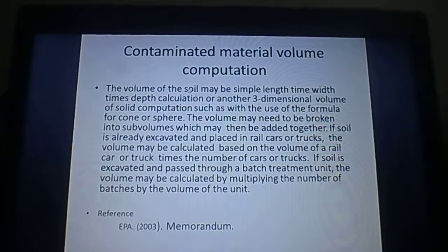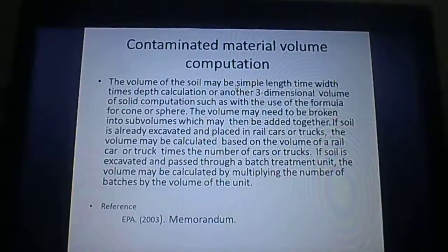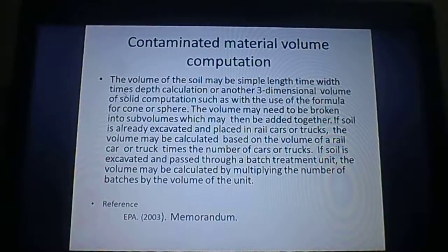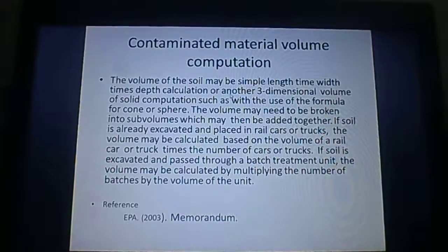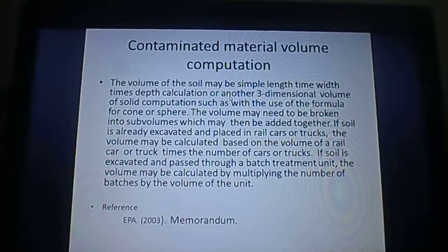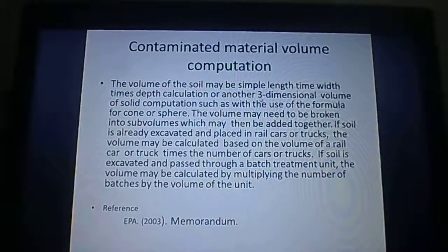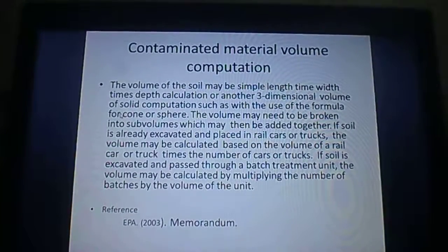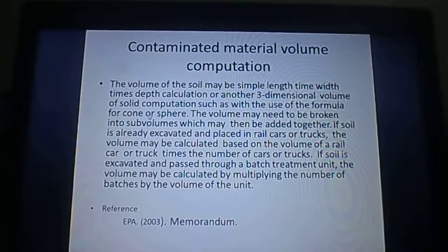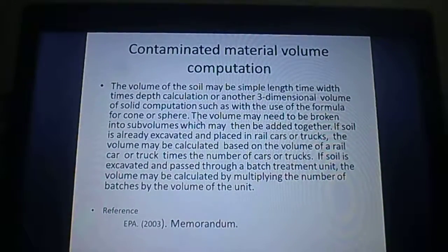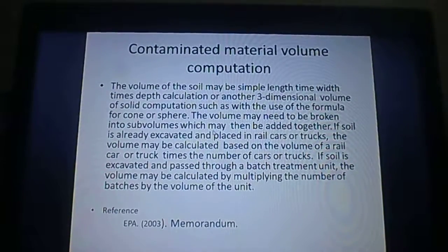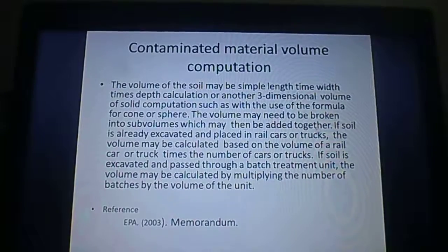The volume of the contaminated soil may be calculated by plainly multiplying the length, the width, and the depth, or by solid computation, such as with the use of the formula for the computation of the volume of the cone or the sphere. The volume may need to be broken into sub-volumes, which may then be added together.